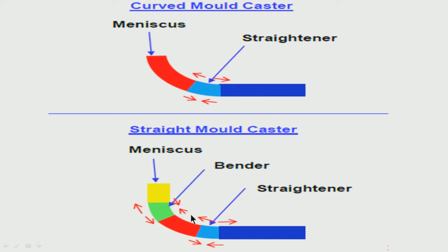So, the stresses on the shell will be something at certain locations, and at the opposite outer radius it may be something else. It may be tensile here, it may be compressive here; here it is compressive, there it is tensile. These aspects I will discuss later on when we come to the continuous cast quality, whether there will be cracks and all, but right now try to understand what is happening.